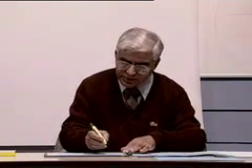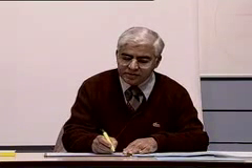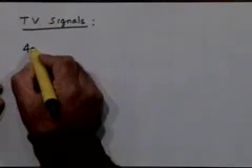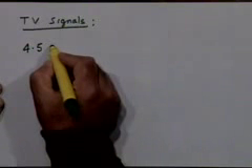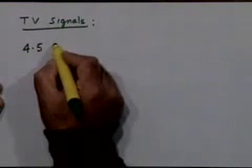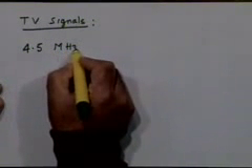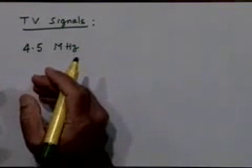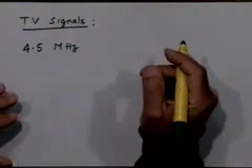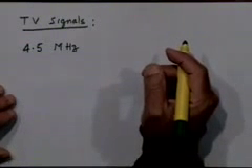Typically, it turns out, and this is a good point for comparison with the other signals, for the TV signal the bandwidth requirement is to the tune of 4.5, not kilohertz, but megahertz. So as you can see, it's 3 orders of magnitude higher than the bandwidth of a speech signal. So bandwidth requirements of a picture signal will be much higher than those of a voice signal.